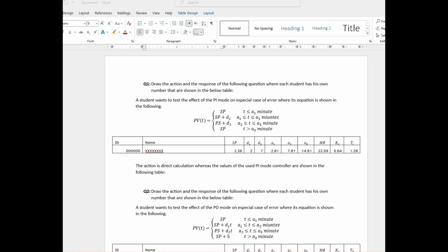We just disconnect the wires of the first element from the loop and put another device. We call it a simulator sometimes. An example of this simulator is a current source, and we adjust this current source, or a HART communicator, or whatever simulator we can use, and we try to adjust it to send a signal with our settings.